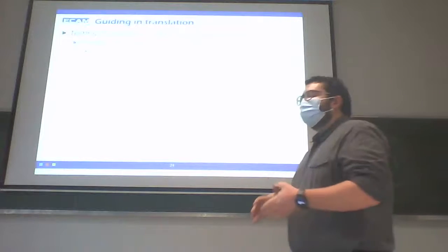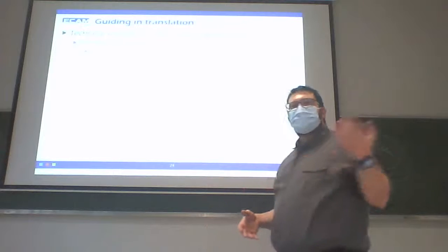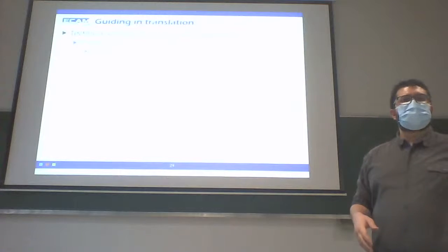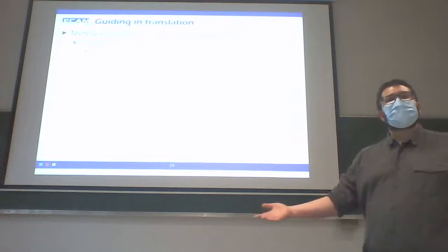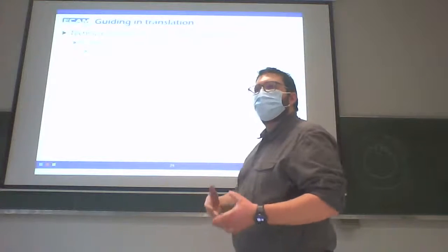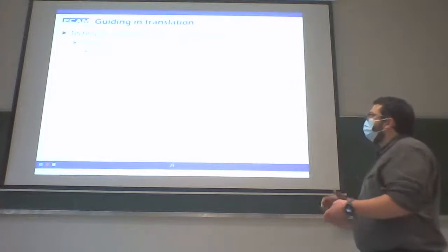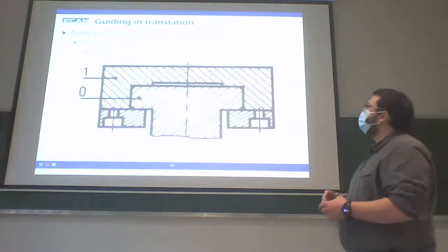Next solution will directly use the shape. At the beginning we used a cylindrical surface plus a rotation stop. Here we'll use directly a shape that stops all the movement except this translation. So the first one is the T form.